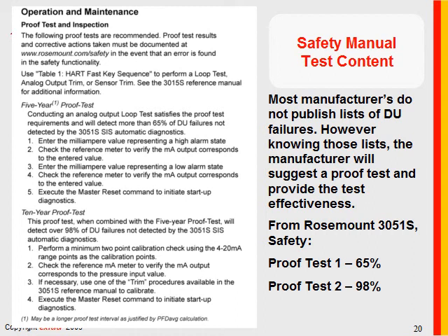And they've defined the 10-year test, which is the proof test, and when you combine this test with the analog output loop test, you will get 98%. So you would have to perform the first test, also known as the 5-year test, and then perform a minimum 2-point calibration check using the 4 to 20 milliamp range point.